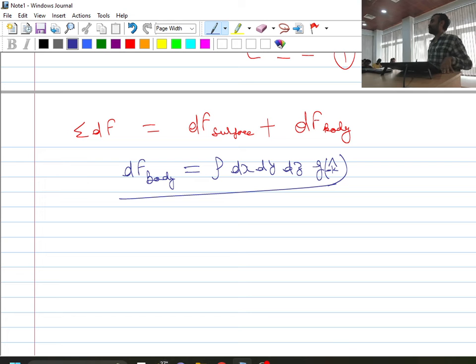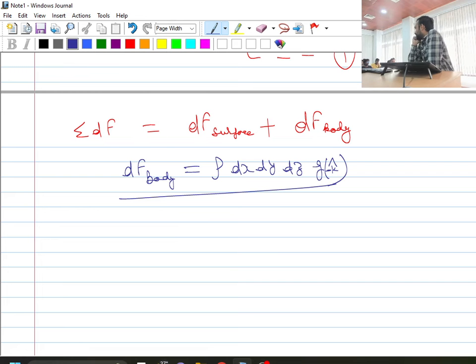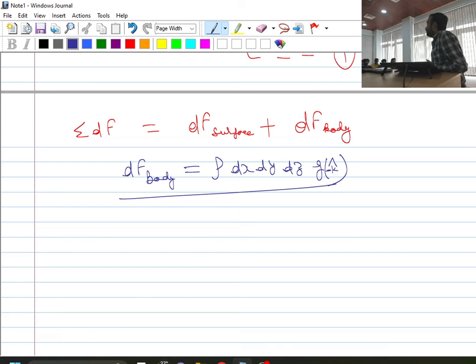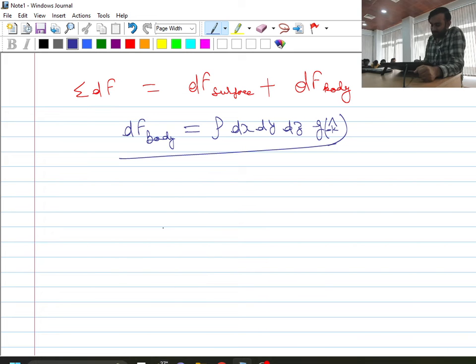Now what about surface forces? Pressure and viscous. So an important point is, till now whenever we were studying the surface forces, we were only measuring the effect of the pressure force. Either we were saying that surface force is included as a whole total term, or it is included only because of the pressure term. So the viscous term is something which we have not dealt with that much clarity.